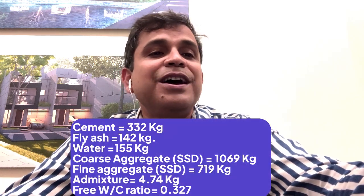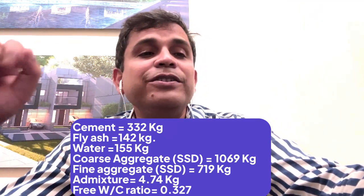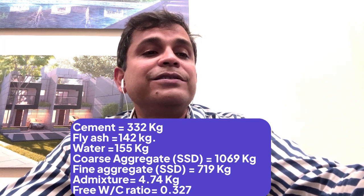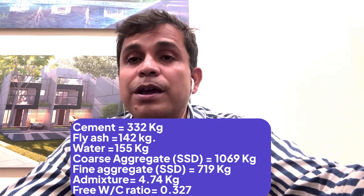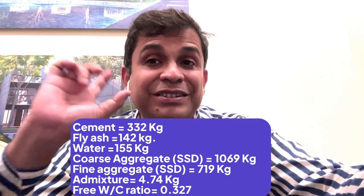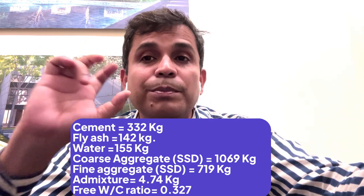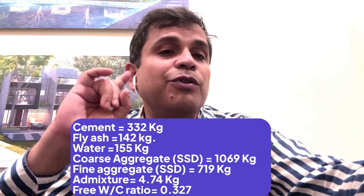So, here I have an example. In this example, I have cement equal to 332 kgs, fly ash 142 kgs, water 165 kgs, coarse aggregate in SSD condition 1069 kgs, fine aggregate 719 kgs, admixture 4.74, and water cement ratio 0.327. Now, when calculating the moisture percentage in the mix, I found 4% for the fine aggregate and 1.5% for the coarse aggregate.